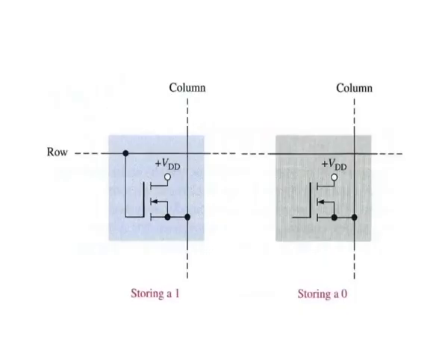Figure shows MOS ROM cells. The presence of a connection from a row line to the gate of a transistor represents a 1 at that location, because when the row line is taken high, all transistors with the gate connection to the row line turn on and connect the high to the associated column lines. At row/column junctions where there are no gate connections, the column lines remain low when the row is addressed.